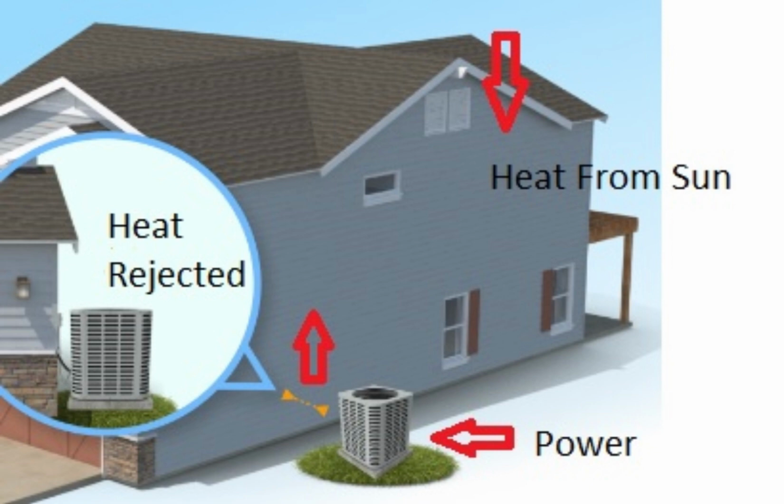And what I'm saying is we'll take that energy, and when we reject it outside at a higher temperature, we'll recover that energy to generate electricity. One way we check that our measurement is accurate is that the energy rejected outside, out of the condenser, has to equal the amount of energy absorbed within the house and the amount of energy pulled in from the grid. These all have to balance out in the end.